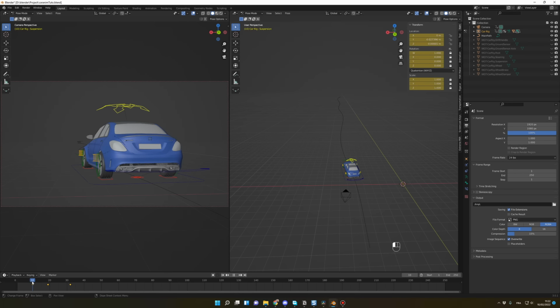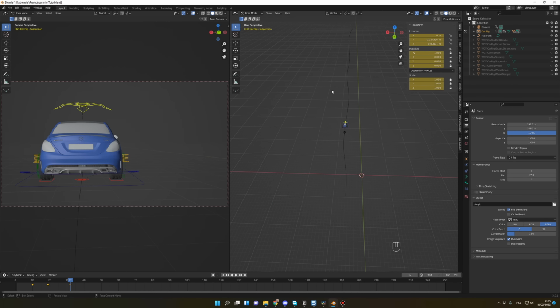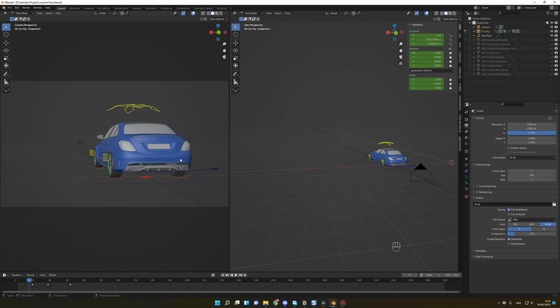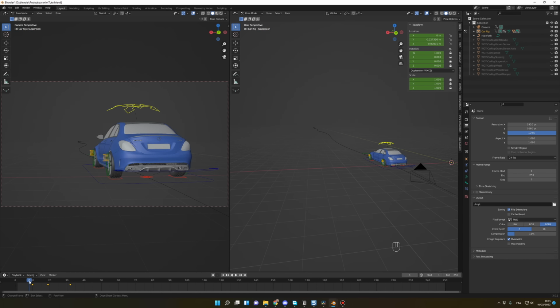All you have to do is to create one keyframe at position 0, then you go in the middle of your curve and you move this control until you have something you like, and you add another keyframe and then the last keyframe to go back to the origin. And you can do that for all the curves you have on your path. And this is why I wanted this camera on the back already, because I know that the final camera animation will be from behind. So now I can already check if it's looking good. Even if it's not the final camera animation, I can already tell that it's working for me.